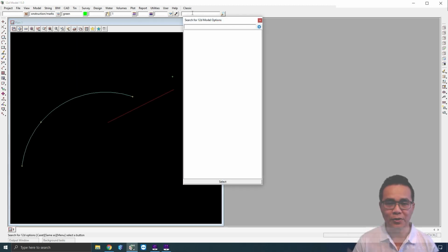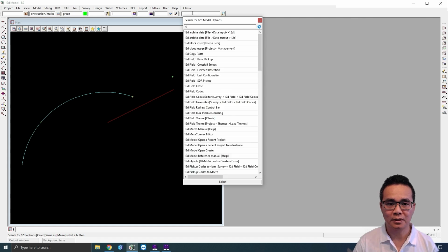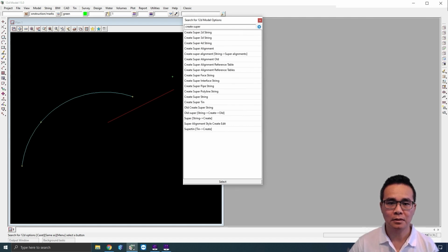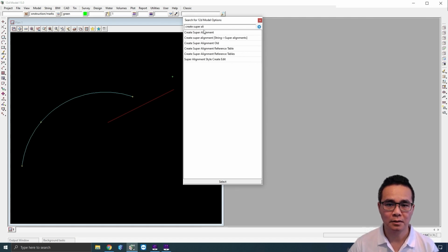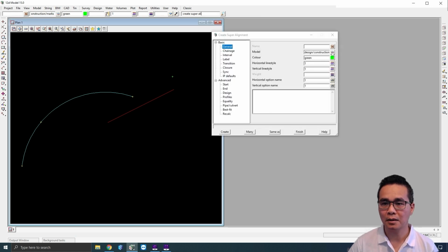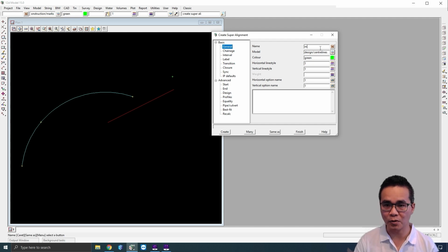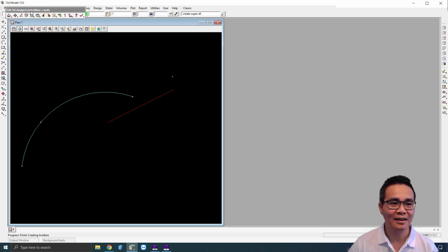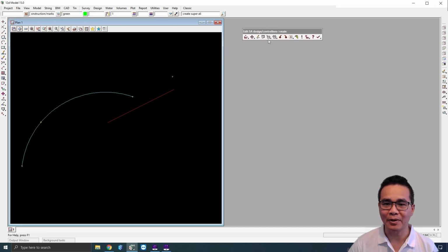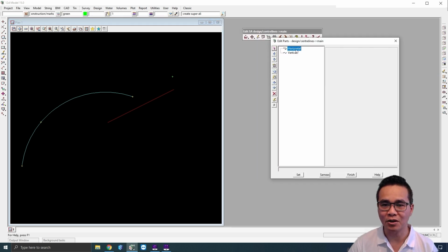Right. I'm going to create a new supplement. Going to select a model for it, center line, and give it a good name, main, create. I'm going to recreate the challenge here, so I'm going to see how many clicks I need to create a 3-point arc.